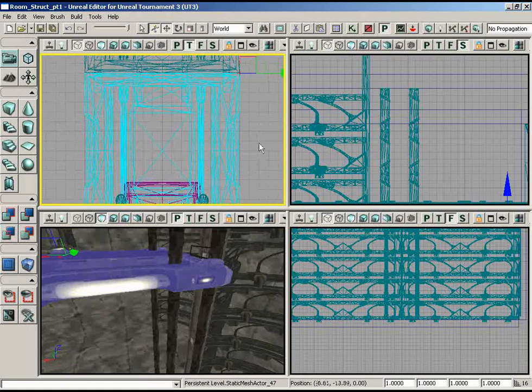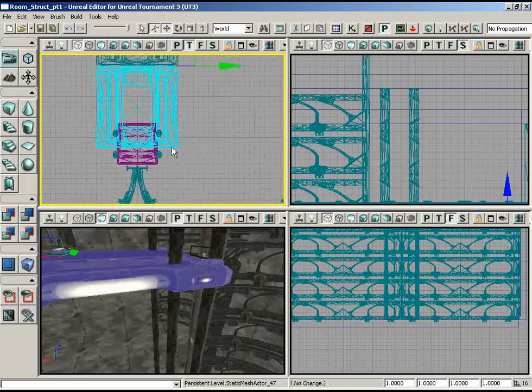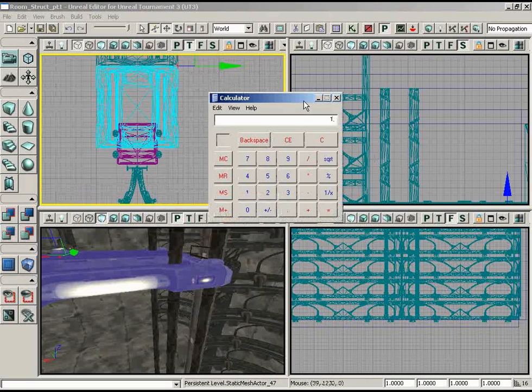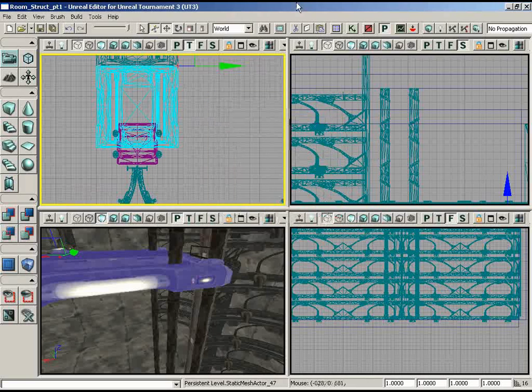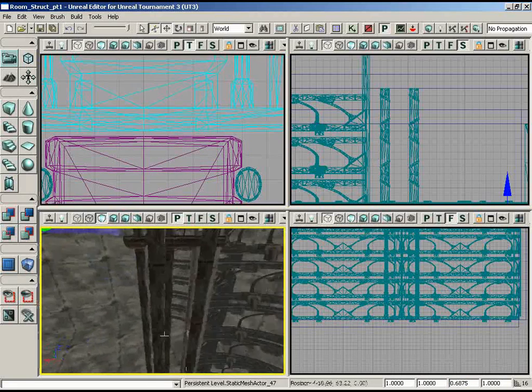And it looks like, let me do a measurement to see how much we need to scale it. We need to actually hit about 192 goes too far. 176 looks good. That'll leave just a small gap for the lift. So bringing up a calculator, if we take 176 divided by 256 gives us a scale of 0.6875. So let's plug that in to draw scale Y. And if we zoom in, that gives us a very nice gap for the edge of the lift.